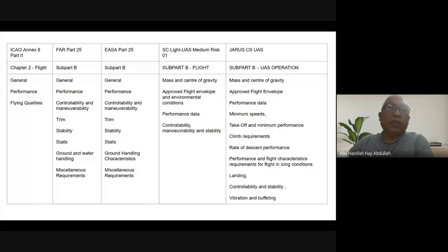So I'll try to keep some example. For the large transport aircraft, we will try to also discuss on modification, big modification, and how the modification affected this design, affected this airworthiness standard, and which we as engineers working on designing the mod, the repair, need to look at this airworthiness to ensure we still comply, because when you do some mod repair on the aircraft, we may nullify the COA until the mod and repair is approved by the authority.